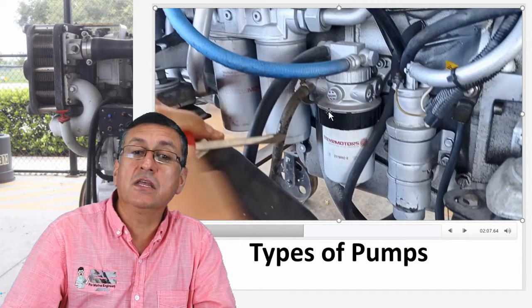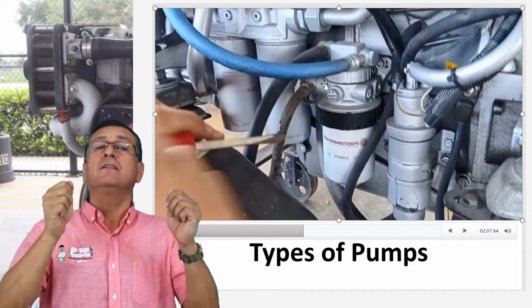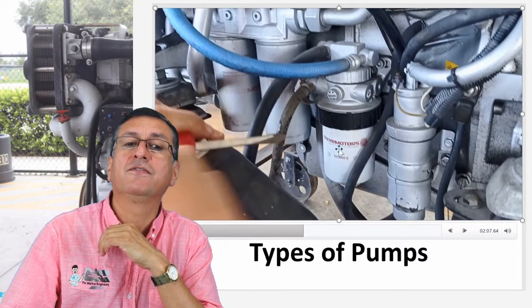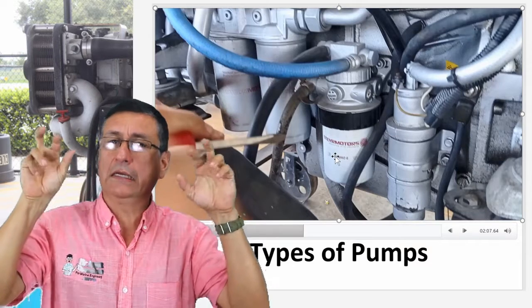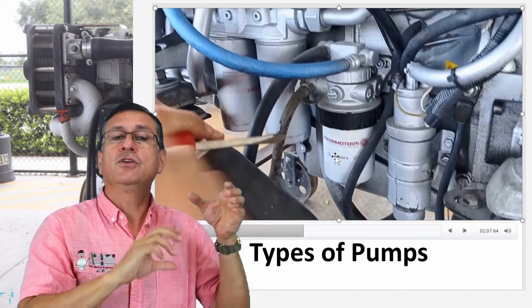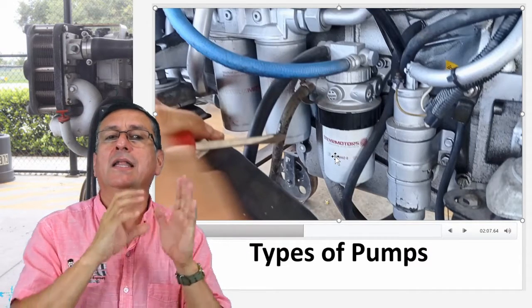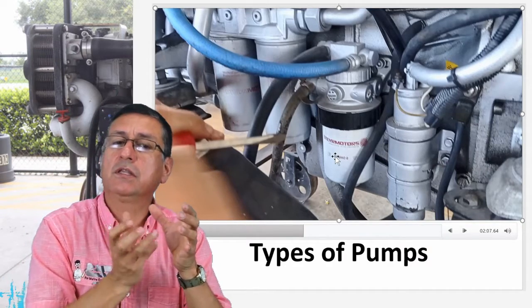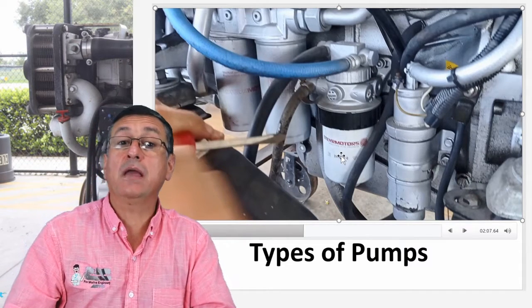And additionally, in this bracket, you have the bleeder. This is the valve to bleed the system, to eliminate the bubbles, especially when you replace this filter. Can you refresh for me what is the procedure, what is the tip when you replace that secondary filter? Yes, you add in the bottom a little amount of motor oil, and on top you introduce the fuel, and you screw on the filter with your hand. That's it. Okay, my friend.